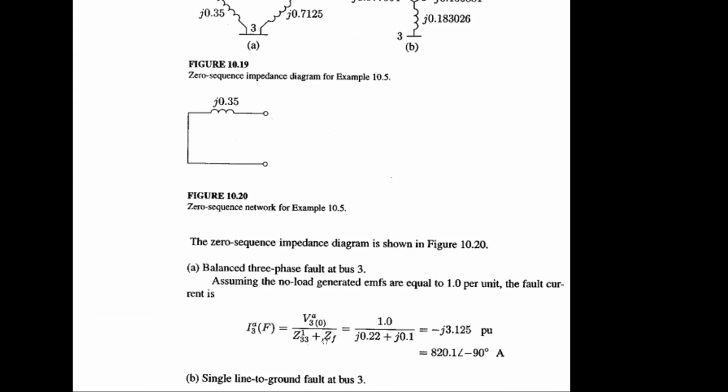And also fault impedance is there. Sometimes regarding that fault impedance ZF, it might be mentioned that it is a bolted fault. A bolted fault indicates ZF as 0. But for this case, as ZF has a value, it is not a bolted fault. It is mentioned in the problem identification, the earlier part, ZF is 0.1. But if ZF is not 0.1, it might be a bolted fault case sometimes. That means you don't have any fault impedance for that fault path.